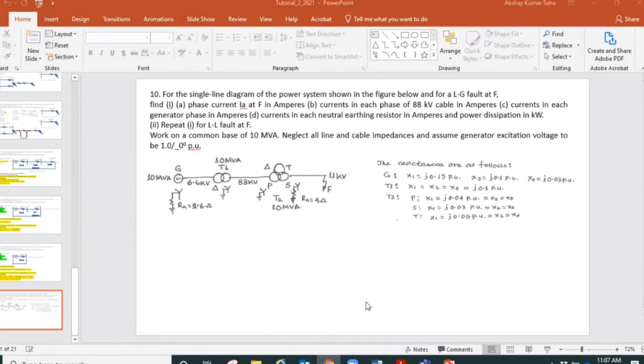If it was a perfect sine wave, and if we analyzed that sine wave using the Fourier transformation that you learned in mathematics, a pure mathematical sine wave, sine omega t, we would see that it has only one frequency component, which is the fundamental, 50 Hz only, or 60 Hz only, or 30 Hz only. But in real life, we cannot have that. We always have steps in it.